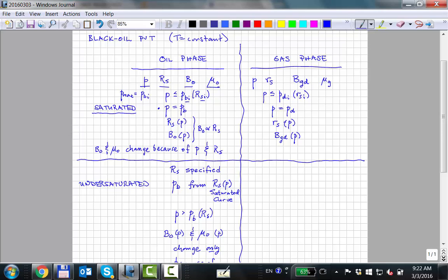Basically, it is a solution of a set of equations numerically. Nobody does this analytically. So you're solving these equations numerically, and each time you solve, you discretize the reservoir, the pipe, or the flow line into small pieces, like pieces of Lego. And for each Lego, each piece of the calculation, all you know is what the system composition is, which is the total GOR.